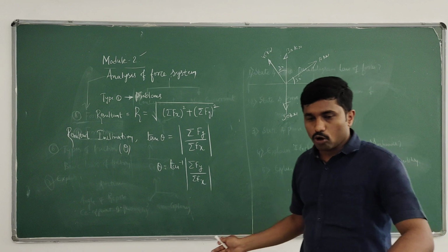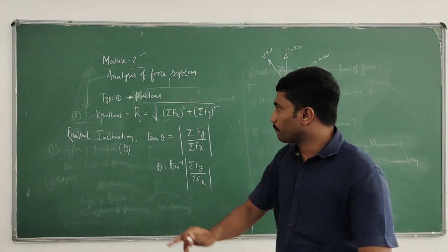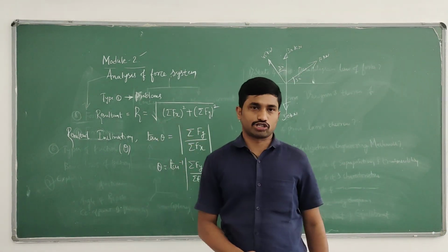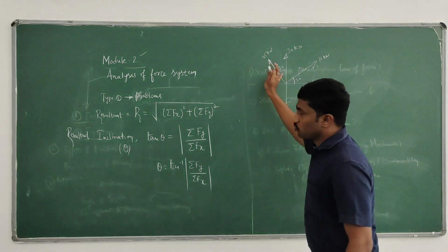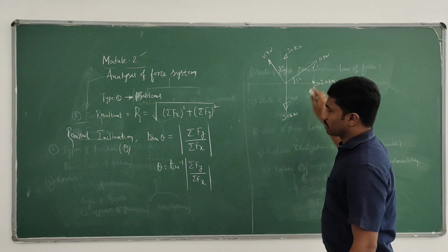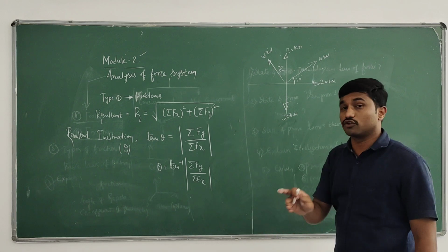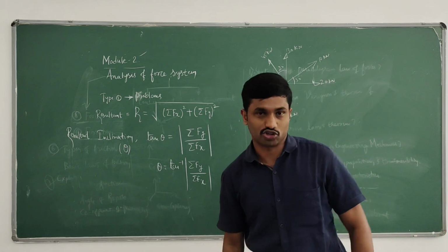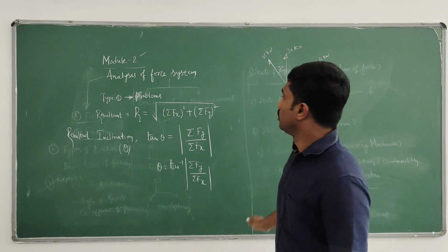They may give a direct problem. They will ask you to compute the resultant and its inclination. In this case, you have to resolve the inclined forces and take whatever horizontal and vertical forces are given as they are. Use proper sign convention. It is very, very important.